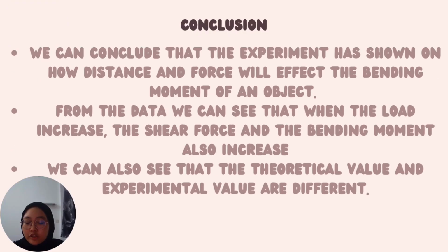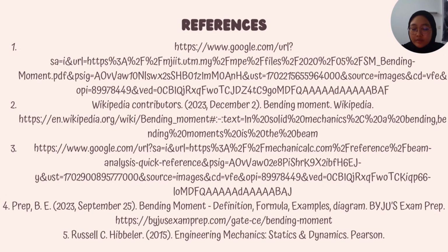In conclusion, the experiment has shown how distance and force affect the bending moment of an object. From the data, we can see that when the load increases, the shear force and the bending moment will also increase. We can also see that the theoretical value and experimental value are a little bit different. Since the percentage error is less than 20%, we can conclude that this experiment is a success and the objectives were